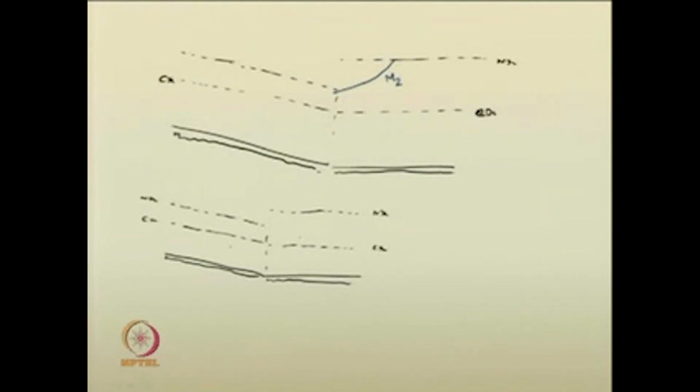In this case one can imagine, say from here the water surface profile changes like this, and partially it becomes M1 here and partially it becomes M2 here in channel 2, like that. You can visualize these things. Whether this is also theoretically possible or not, you have to think on yourself. We will discuss that further. The third case is, this is case 1, case 2, third case is